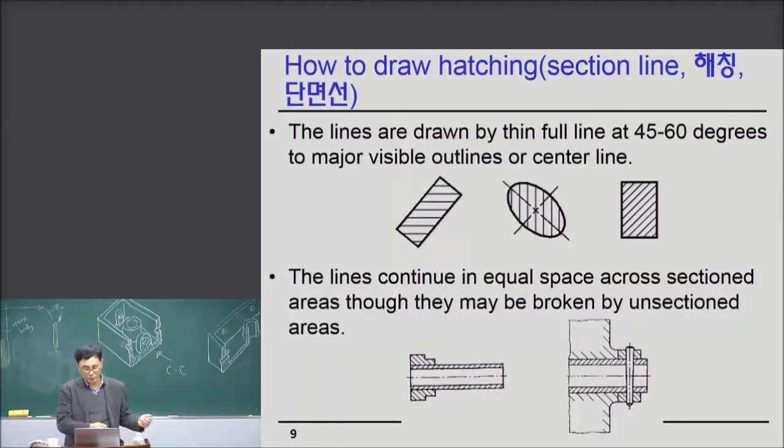When you transfer the drawing and give it to the technicians in the field, then the technician will understand. If without hatching, then he will understand that, oh, this is a pin. Okay? So never apply hatching line to pin or key.